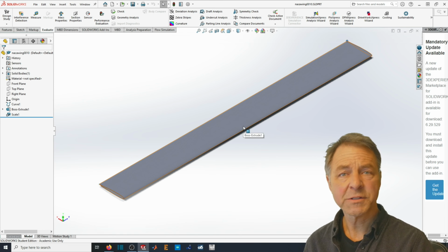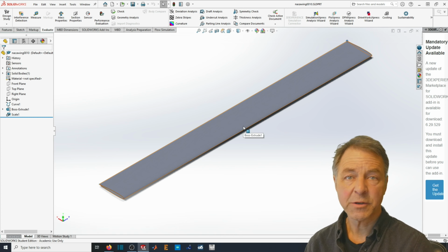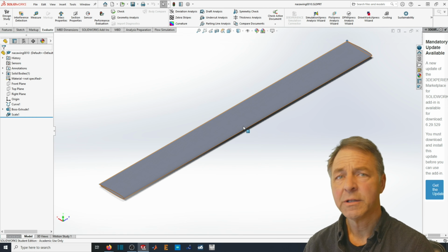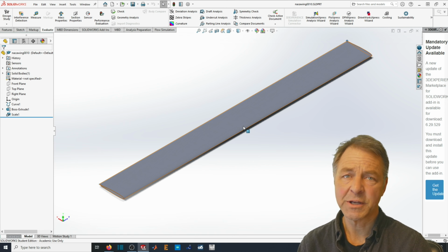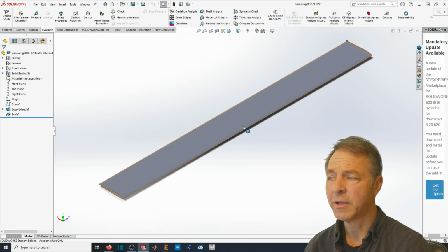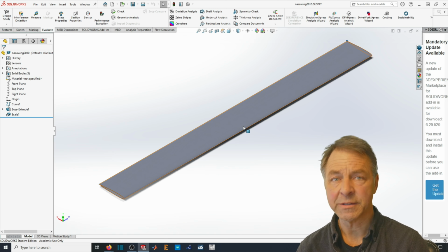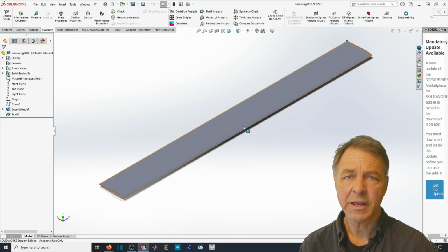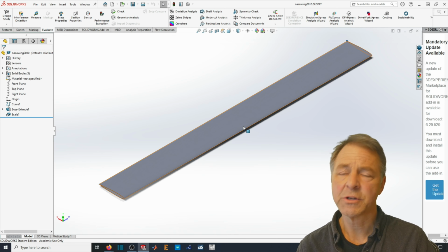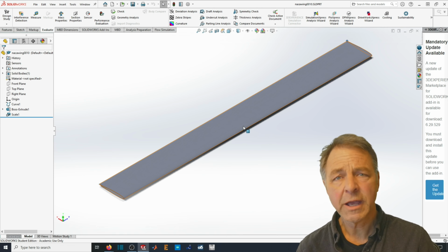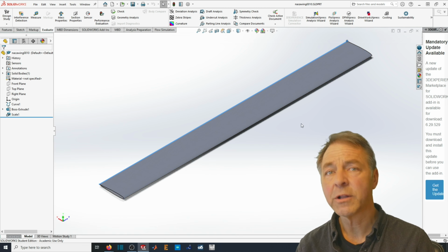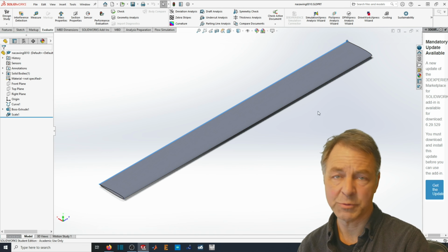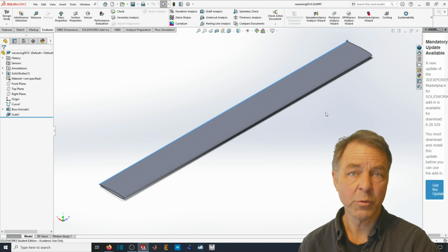The reason I'm making it a long skinny wing is because the basic wing models are assumed to be two-dimensional, and the air tunnel testing, wind tunnel testing that was done to get the data that we used to compare with was done on long slender wings. So the theory is for long slender wings, and the test specimens that we compare with for drag and lift coefficients were long slender wings. So our CAD model should be reasonably close to that. Not a very elegant and exciting CAD model, but let's just see how close we can get this result to the real world known result.